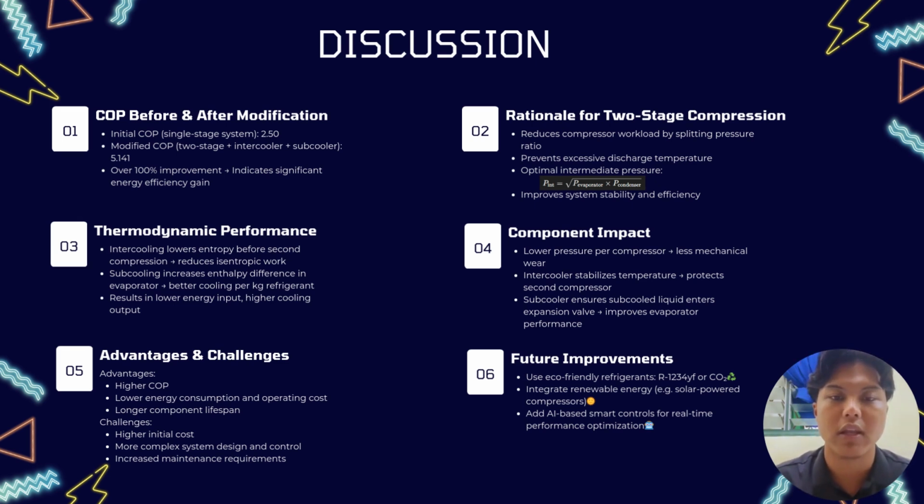However, we also identify several challenges. Adding a second compressor, intercooler, and a subcooler increases the system's complexity and initial installation costs. It also requires more advanced control systems and regular maintenance. These are important considerations when applying this design to real-world applications.